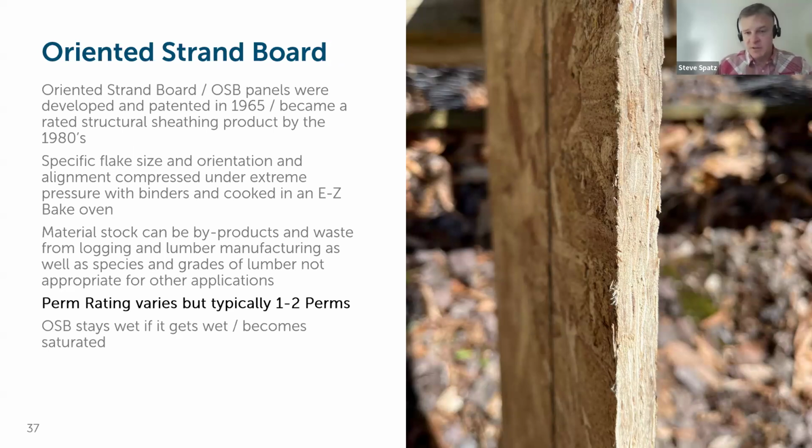Air tightness is also differential depending on the manufacturer and the wood types and composition of OSB as well. Under pressure, it's been tested to be both airtight and somewhat leaky. So there are different characteristics to consider when choosing OSB versus CDX.